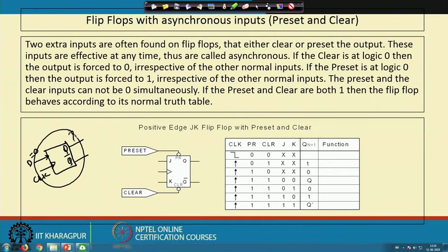If I make a circuit like this and switch on the circuit, then what will happen is that this Q and Q bar will pick up some arbitrary values, and from that point onwards, depending on the D value, it will go on operating, but the system behavior will become unpredictable. For the SR latch we have seen that we should not apply the pattern 1 1, but we do not have any control over that.